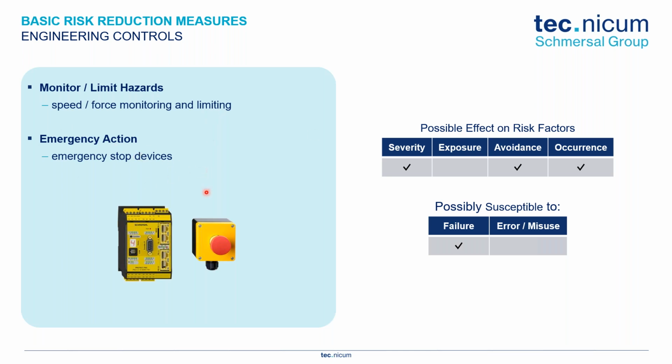The emergency stop functions. Okay, again, there's standards for this. There's standards if we're looking at a collaborative application, to help us determine what are appropriate speeds and forces. For e-stops, there are standards to let us know what an e-stop function has to have, right? Red mushroom, yellow background, self-latching, manual reset, remove all hazard energy. Okay, so there are other standards that we have to consider if we're selecting these certain options.